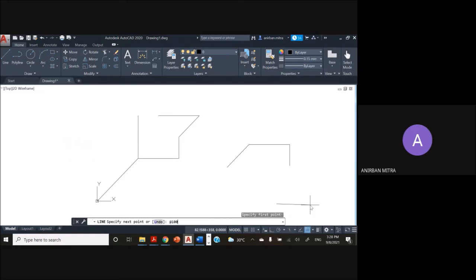Now you decide, and it is quite open to your personal choice as well, whether you want to go for Cartesian or polar relative system. You can provide comma 0, or if you want to go for polar, then angle 0. That is the first line. You want to move vertically upward now. So @ 75, angle 90, enter.